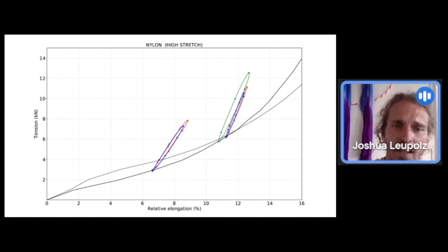And then what happened, he had a base tension of 2.5 to 3 kilonewton, and he dropped a heavy weight into it. I think 75 kilograms, 1 meter free fall, whatever. So it's roughly a leash fall. It's a pretty hard leash fall, so you get peak forces of 7 kilonewton. The blue and the white lines are just different weights, which for this moment doesn't matter too much.